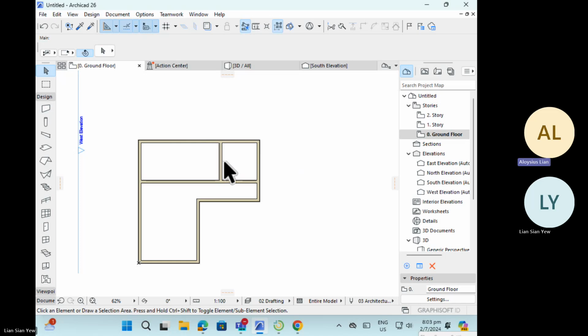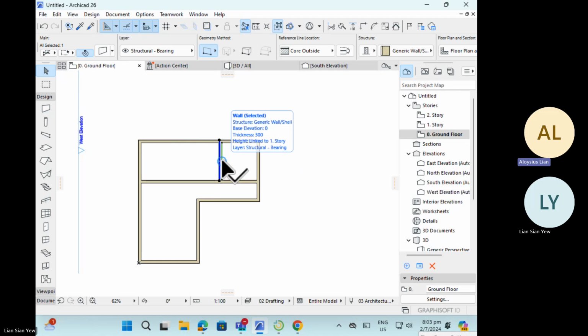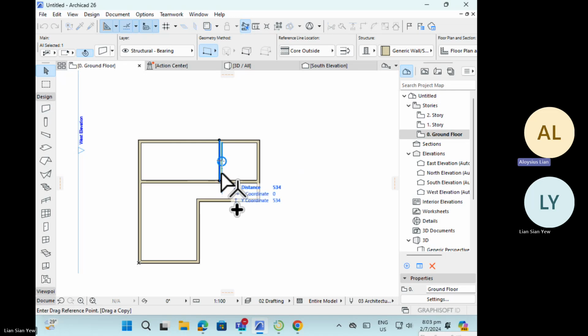The next step that we want to do, right, is to copy this wall to the left. So just now I was showing you the hard way, which is to click on the blue line, wait for the palette to come up, and then use the array tool to copy, right? So the fastest way is to use the keyboard, Control-Shift-D, right? And then you will see that now my cursor has a plus arrow below. And you can essentially click, and then move your cursor to the left, and you can just type D, which is the shortcut to go to distance, and type 2250, enter.